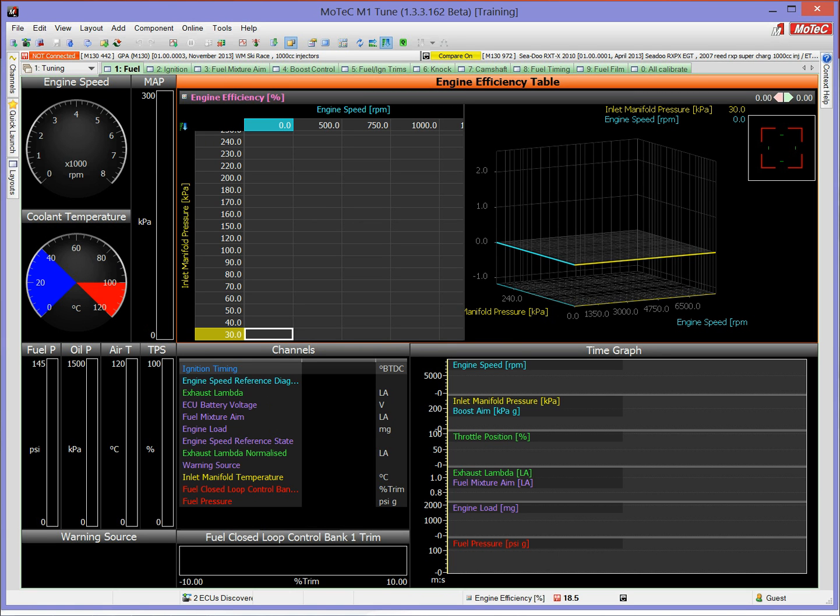Now, that method, the migrating data method, is handy to bring over all sorts of things. I might decide that that same file has a 3-bar map sensor that I want to use out of it because the standard map sensor is not turboed. I want to put a 3-bar map sensor, so I can use that migration method to bring that in. I can steal any calibrations or setup parameters out of any file I like and just double click them or pull them over manually.